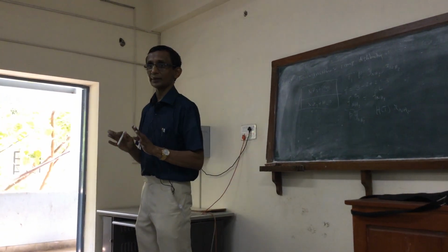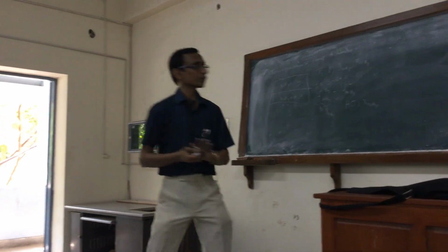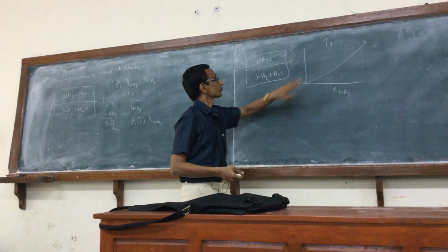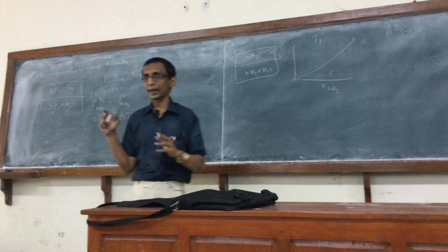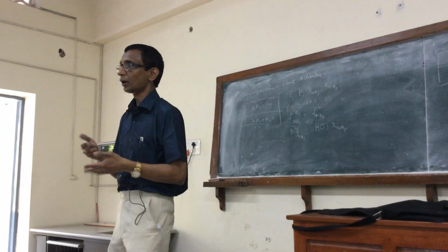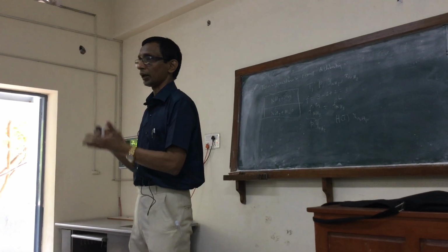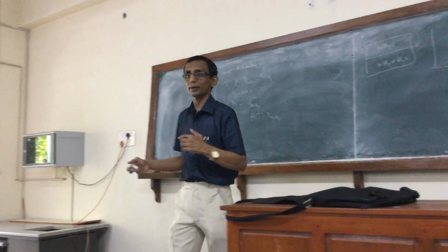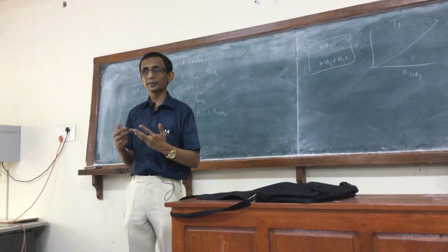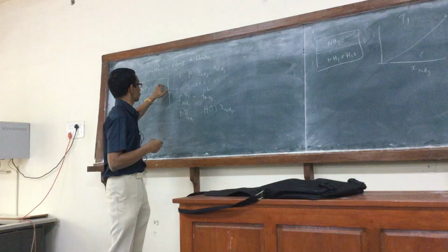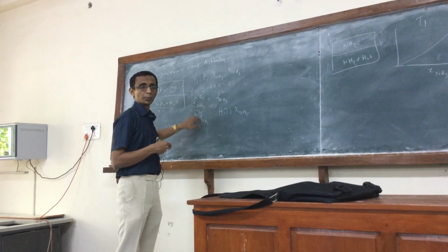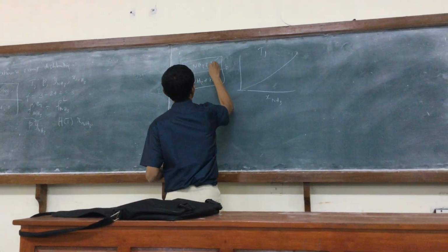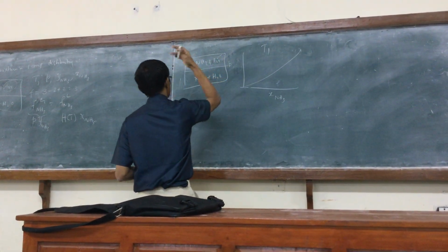The advantage has to be seen here: suppose I am able to generate this data using just ammonia. So I don't need any other gases to unnecessarily mix it. I can conduct a whole set of experiments using pure ammonia, absorb it in water and generate all the solubility curves. Then I can use it for any other system where ammonia could be present in a mixture of gases, provided only that those do not dissolve and the pressure is sufficiently low that the gas phase can be treated as an ideal gas mixture. So various other examples are also possible.